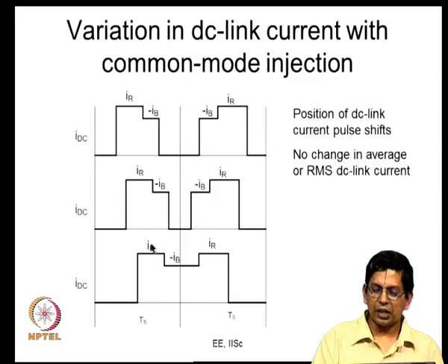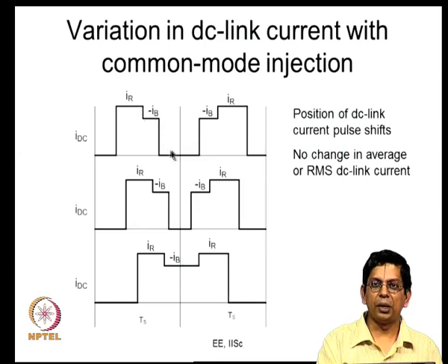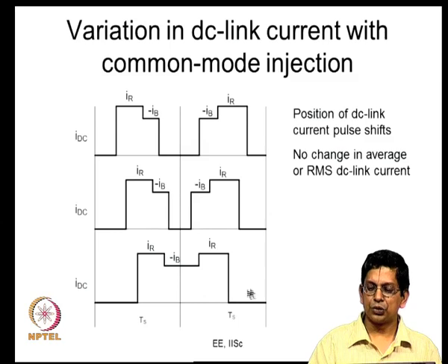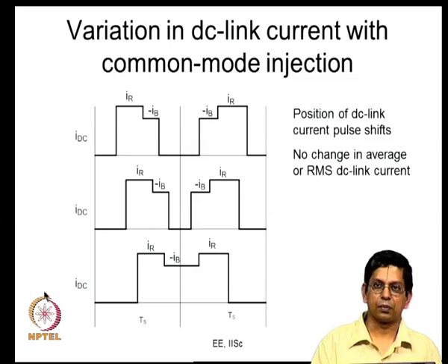So, here again this is IR square, IB square. You try to evaluate this RMS value, you will get IR square into T1 plus IB square into T2, the whole divided by Ts. So, the whole thing under square root would be your RMS value. So, this RMS over a subcycle also does not change. This is true about this subcycle, this is true about every subcycle which is yet to come and every subcycle which has been crossed.